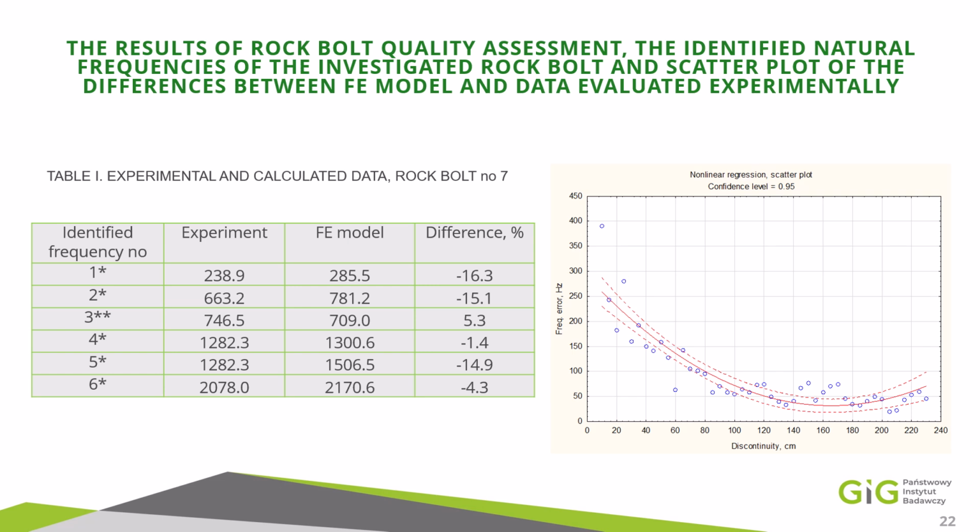Too long a spinning phase damages the contact between the rock bolt and the grout, also in the back part, close to the end, because hardening time in that part is shorter than in the outer part.